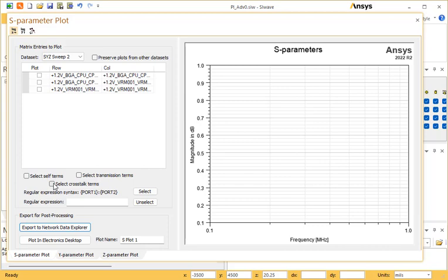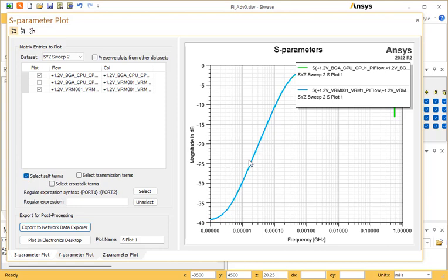If you have so many power planes, then you can look at the crosstalk. Now, what's the problem with the S parameters? These S parameters are normalized to 0.1 ohm. We don't know the impedance of our power planes, and consequently, we know that these results are not reliable. You cannot trust them, because you have to normalize the port to the right impedance that matches your power plane.